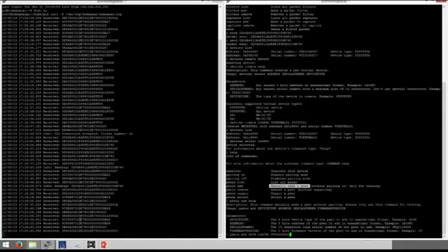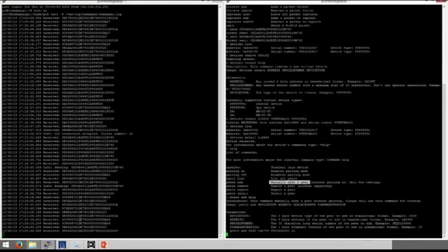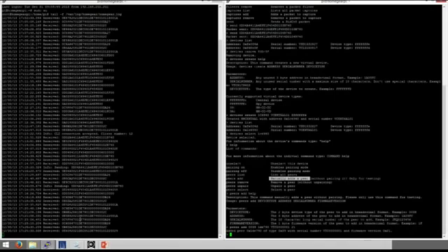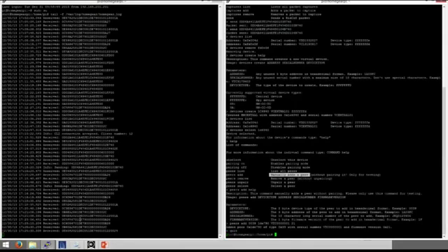And the firmware version, the most current firmware version is 2.1. This information you can also get out of the XML file, or by just inserting a battery in a thermal control, then it will display the firmware version. And now HomeGear knows the thermal control of our victim. We are logging out. We don't need the command line interface anymore. And now we need to tell HomeGear to set the new set point temperature for us.